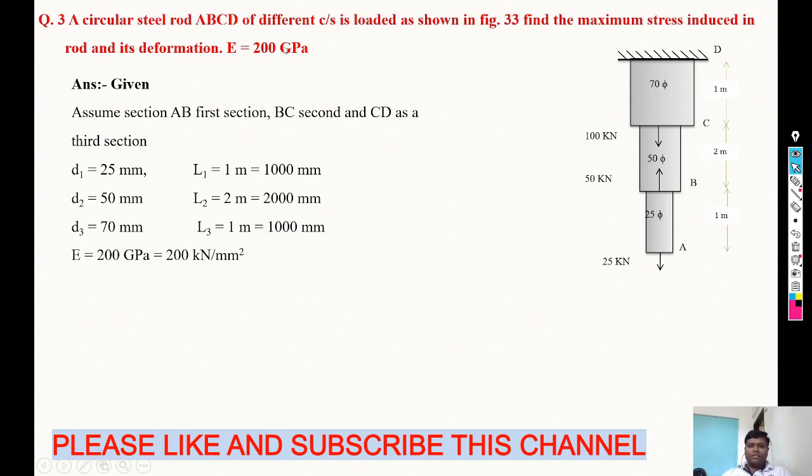E is given as 200 gigapascal, and we know 1 gigapascal equals 1 kilonewton per mm square. So E is equal to 200 kilonewton per mm square. First we require the stresses, and in the elongation formula we also require the area. So on the basis of the diameter, just calculate the area of each section, because we require it in the formula. A circular section is given.